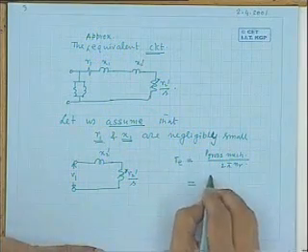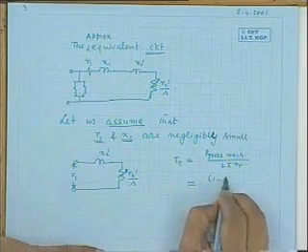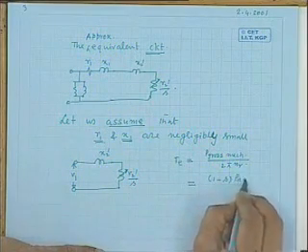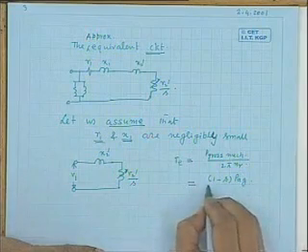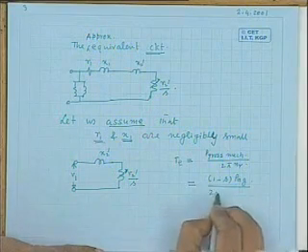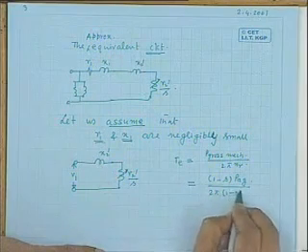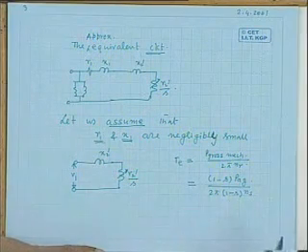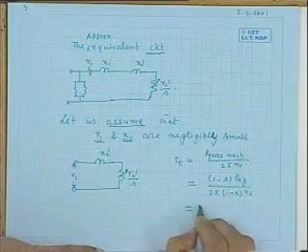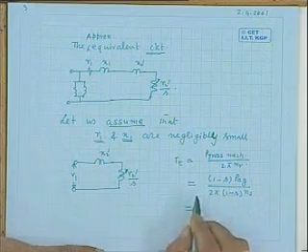Now this P gross mechanical is nothing but 1 minus S into P air gap power, and this I did last time. I will do it quickly. This is 1 minus S into Ns I can write. Therefore the electromagnetic torque developed by the machine will be decided by the gross mechanical torque.